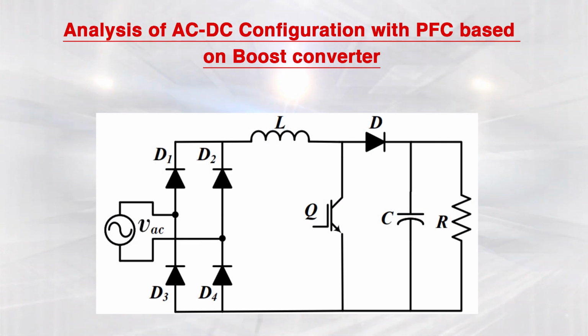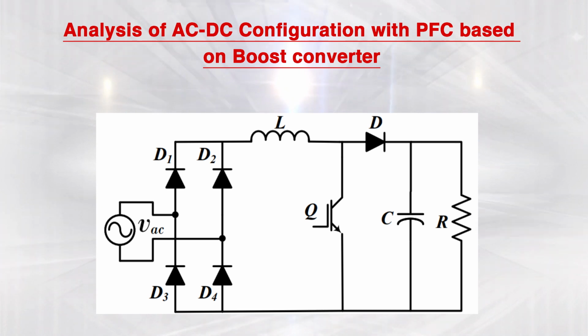So, let us go to the analysis of the single phase unidirectional converter. In the case of the single phase unidirectional converter, as we have seen earlier, we have 3 devices which are used for DC-DC conversion, and simply we have used a diode bridge rectifier over here. If you have not used this power factor correction unit, the DC-DC converter, then the capacitor is directly connected with the diode rectifier and it will look like a voltage step load, and many times if there is no control over there, the supply current will be peaky in nature.